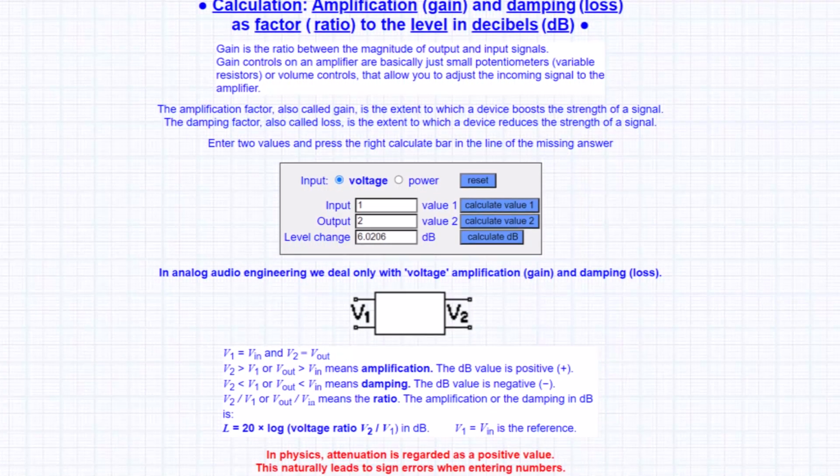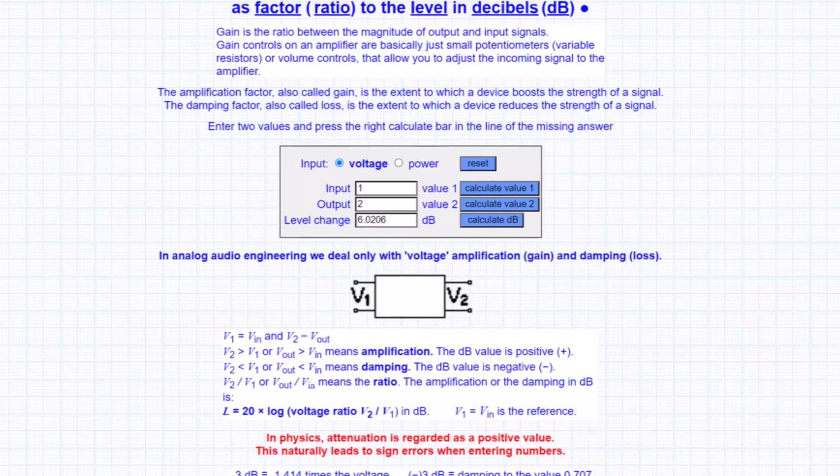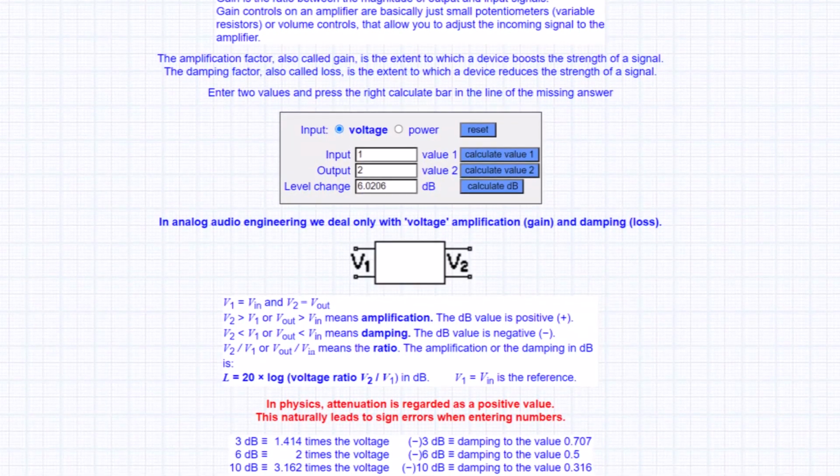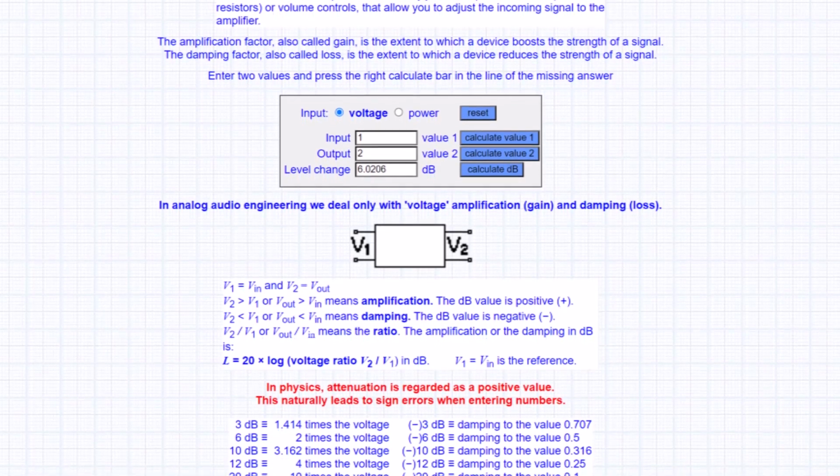In the musical world, we almost never talk about gain as a straight factor, and though it's more common in circuit design and electrical engineering, generally we convert those units into decibels, which is basically an operation of log 20 and comes out to roughly 6 dB being equivalent to 2 times gain, and 20 dB being equivalent to 10 times gain. So if I were to add 6 decibels to a signal, say in my audio workstation program, then I've essentially made that signal twice as loud.